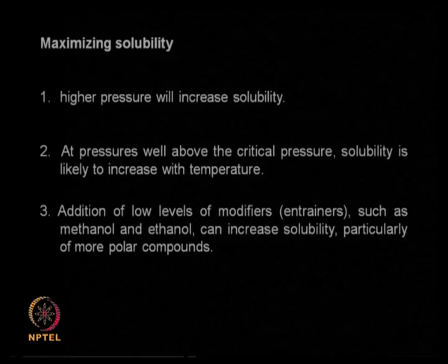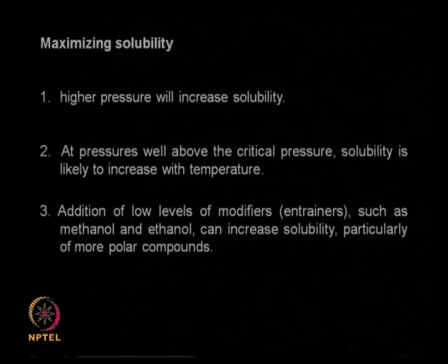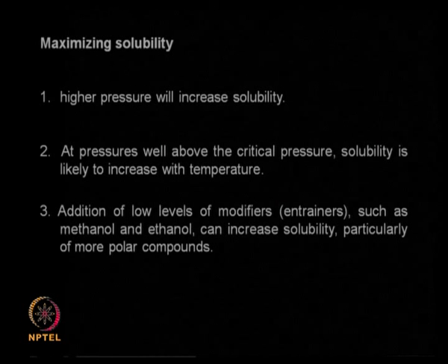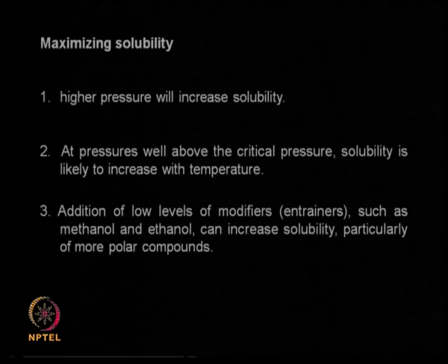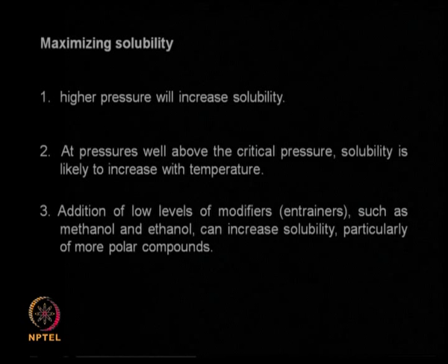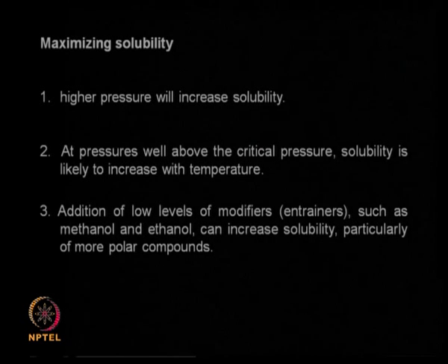How do you maximize solubility? So we can use higher pressure. When you use a higher pressure, solubility increases. At pressures well above critical pressure, solubility is likely to increase with temperature also. So if you are using very high pressure, then the supercritical CO2 temperature also may be very high. So you may have to cool, that means you need to put in a cooling system to cool the supercritical fluid.